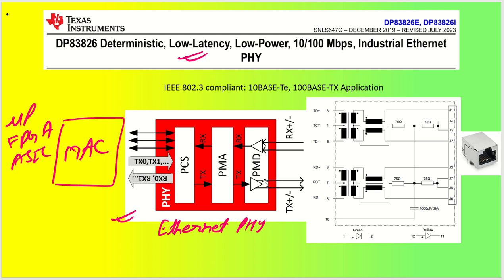And at the same time towards the right side you will see we will have the network, and that is nothing but MDI, media dependent interface. In that case, these are connected to my differential transmission line and differential receiver line, that is RX plus and RX minus, or RD plus and RD minus will be taken.